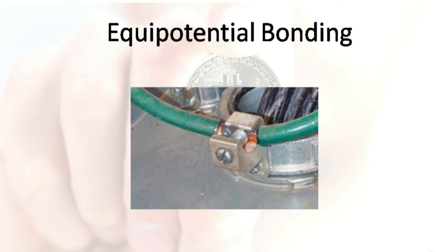If you're concerned with electrical safety, meaning that during an electrical fault, it might cause potential injuries while you are tinkering with the equipment, which, just so you know, is very unlikely given the amount of current and voltage level that it will be at your site. But nevertheless, you can still use electrically rated PPE such as electrically rated boots and gloves to touch the equipment if you have a concern of electrical fault and electrical safety.